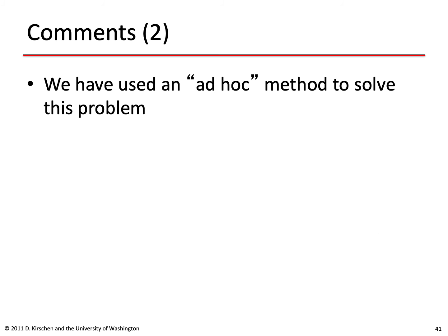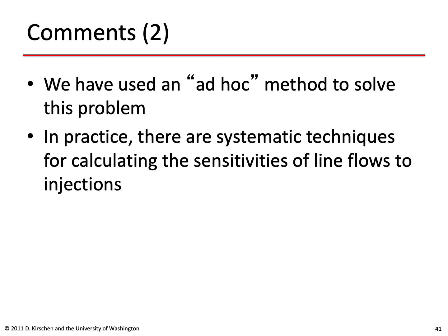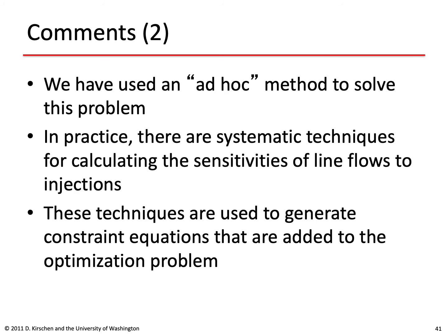The second thing to observe is that we have used an ad hoc method to solve this problem. In practice, there are systematic techniques for calculating the sensitivities of line flows to injections, and these techniques would then be used to generate constraint equations that would be added to the optimization problem and fed into an LP optimization engine.